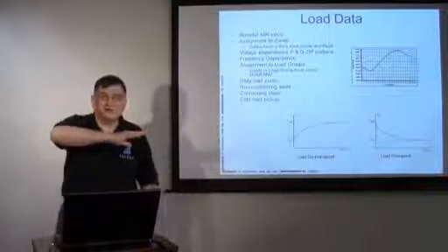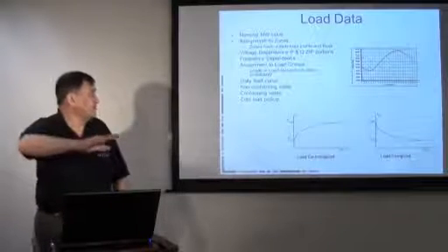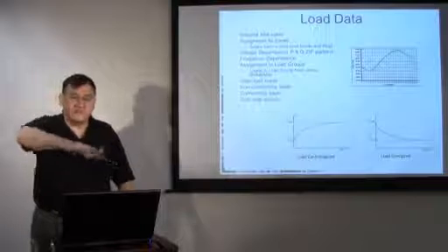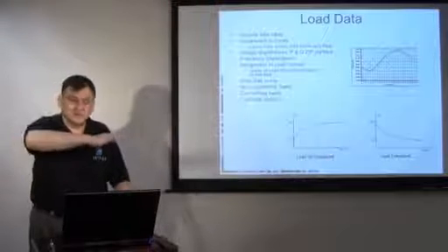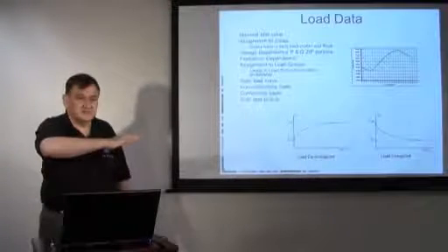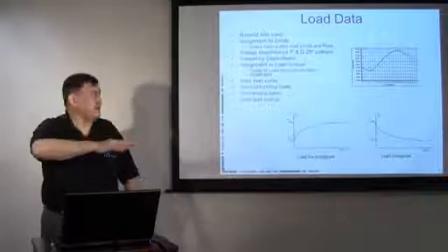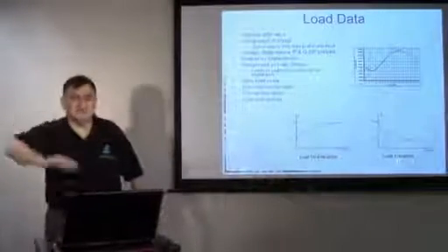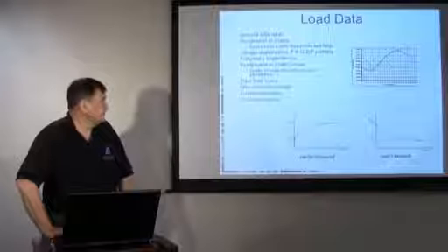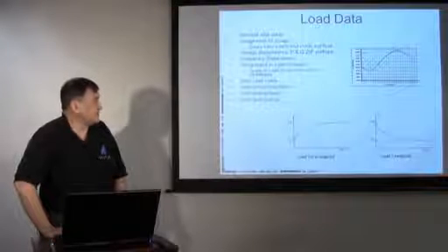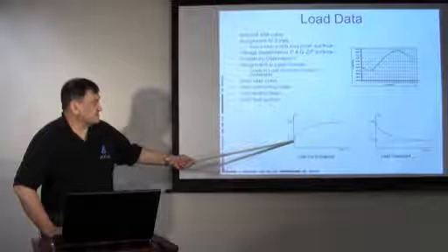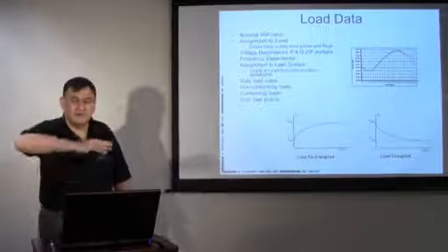Some loads, like a factory or a drag line or an arc furnace, won't follow the normal daily load curve. So a non-conforming component, that load is big enough and its characteristic is so different that you actually have to give it its own particular schedule. And then we have the cold load pickup. When there's a system shutdown, the load is de-energized.